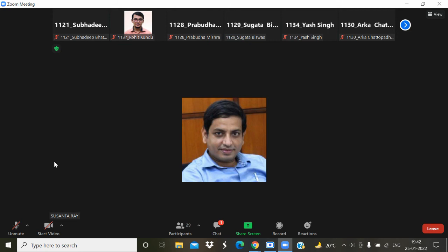Tau is given by pi D by P, where D is the mean diameter of the air gap and P is the number of poles. Assume L by tau as some value between 1 to 3.